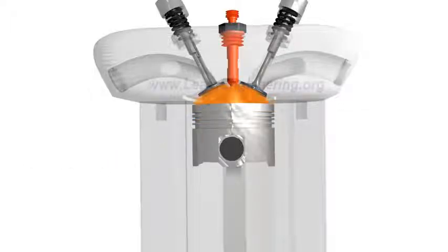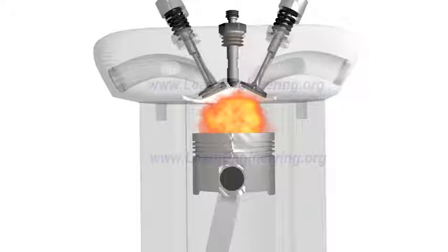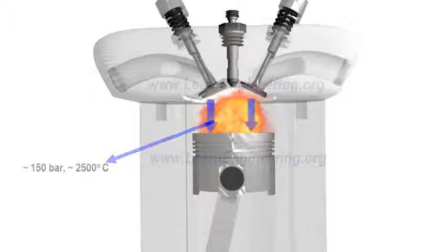An atomized form of diesel is injected into this compressed air. The fuel gets evaporated and undergoes an uncontrolled spontaneous explosion. As a result, the pressure and temperature rise to high-level values. The high-energy fluid pushes the piston downwards.